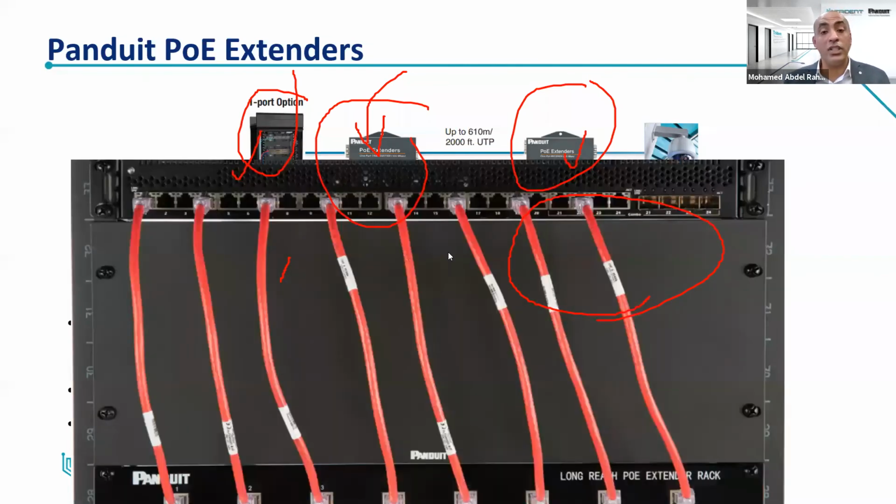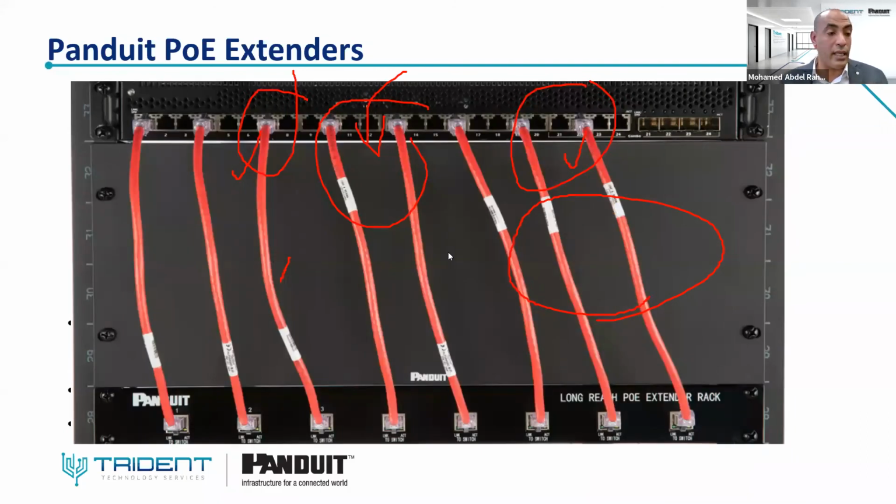Also, another recommendation: when you are going to use a transmitter or the PoE extender transmitter beside the switch, our recommendation is a new product. We now have a transmission panel, or PoE extension panel. It can support up to 8 PoE extender transmitters and can be mounted on the rack. Using a smaller patch cord, you can connect it to a legacy or old non-PoE switch.